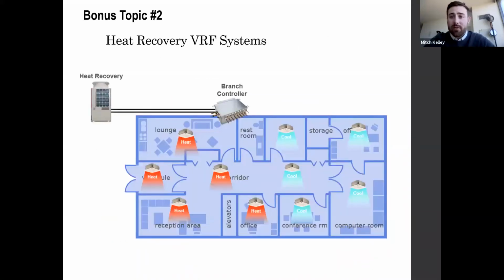Similarly to the water source heat pump example on the previous slide, VRF systems can take advantage of zones that require simultaneous heating and cooling to basically condense refrigerant directly in the heating zone as opposed to the condensing unit. It is important to note that with many manufacturers, ambient temperature loading limits exist that limit the time the system can spend in these simultaneous heating and cooling modes.